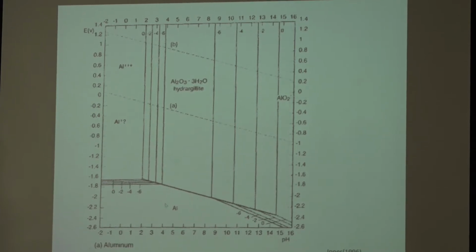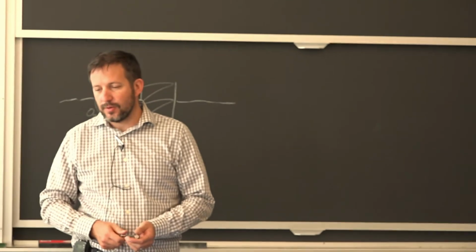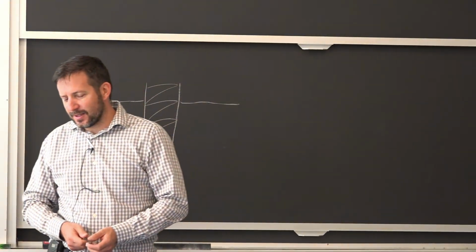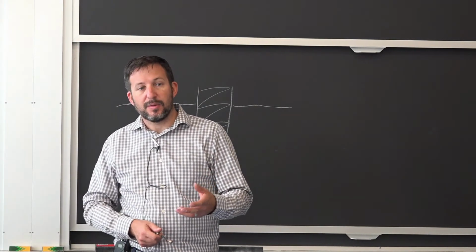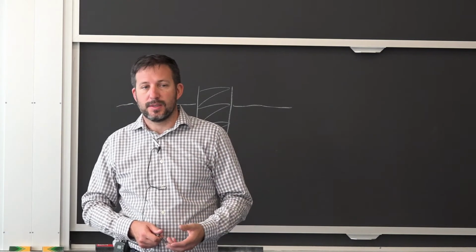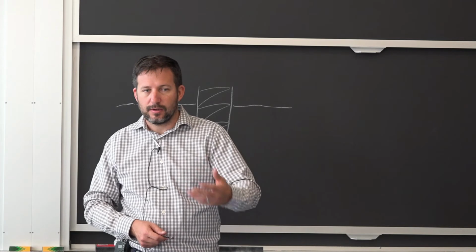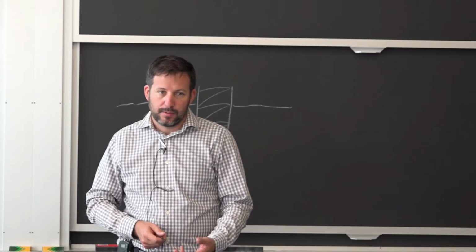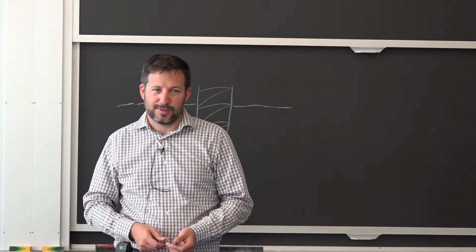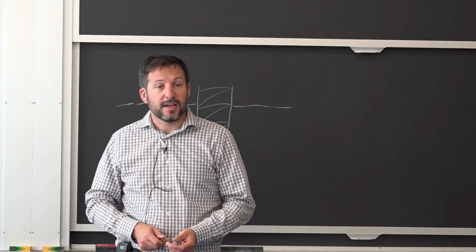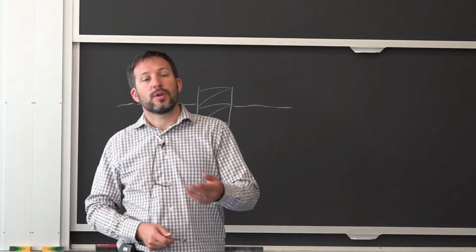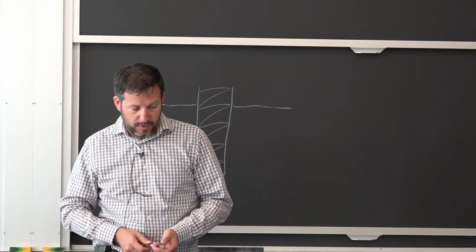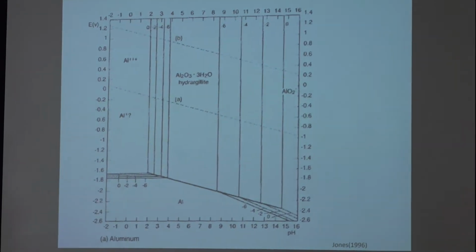Yes? How can concrete have a pH? Okay, very good. The question is about the pH of concrete. I'm not a concrete expert. What I'll say is the cement itself is a basic material, so it's not caustic, but it's in that category. So when you mix that with water and aggregate, you have a high pH. So it's essentially by the composition of the cement, and then you can vary it. You can have grouts that are going to have a much higher pH than the regular concrete to increase that protection. Thank you.